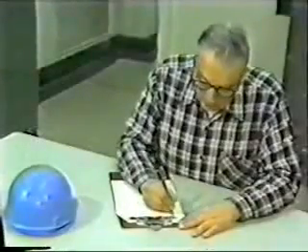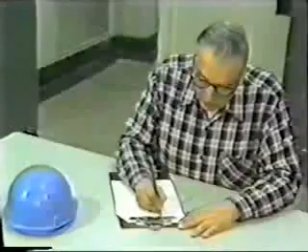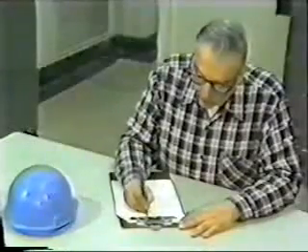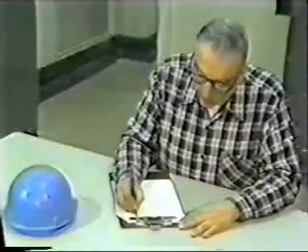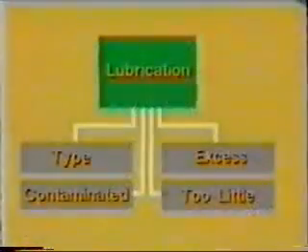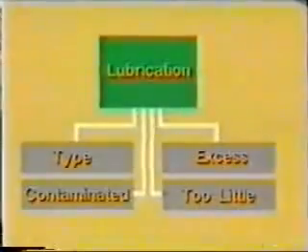Normal operation requires proper alignment. Indications that alignment is proper include a lack of excessive vibration, only one bearing being affected, and a lack of effect on pump function. Normal bearing operation also requires proper lubrication.